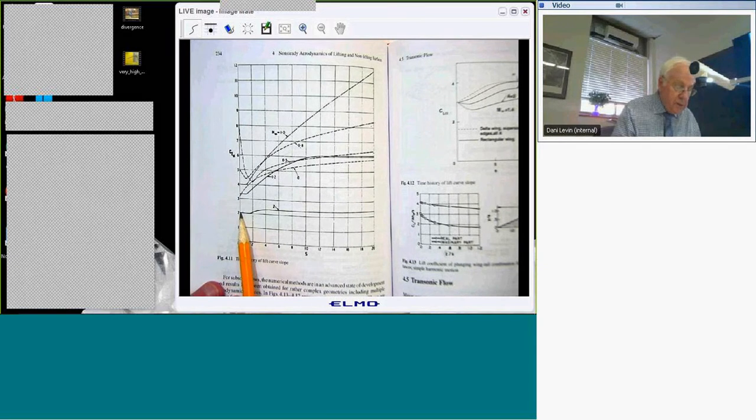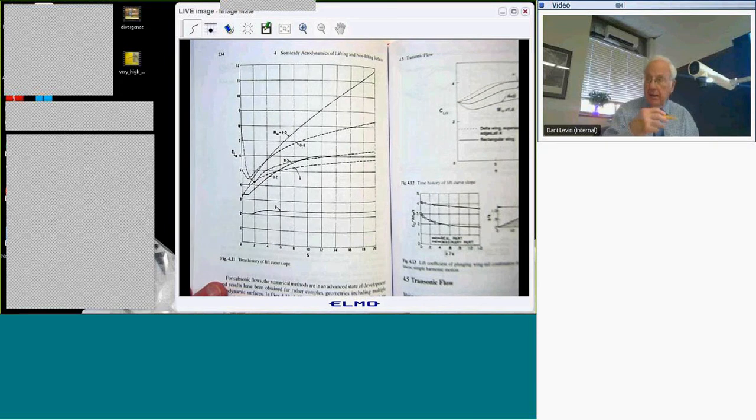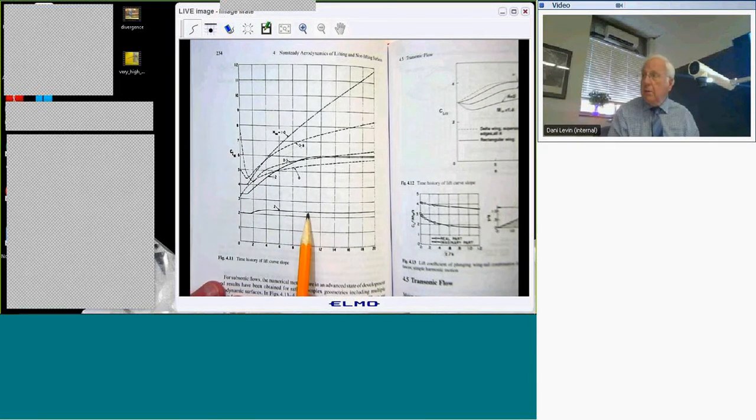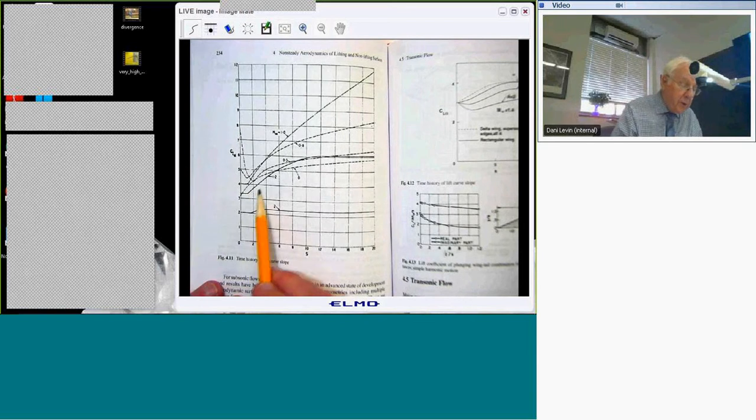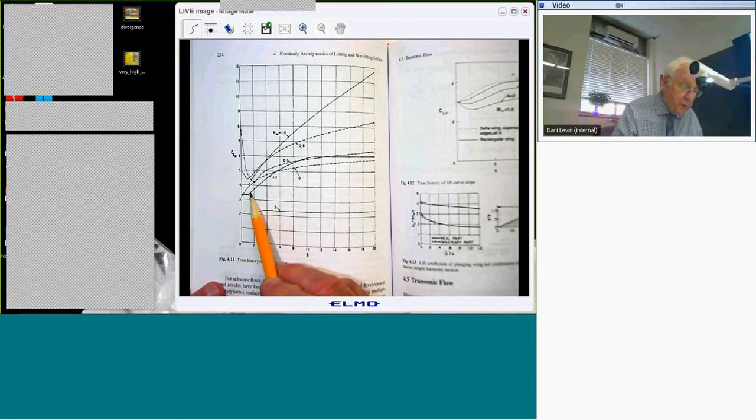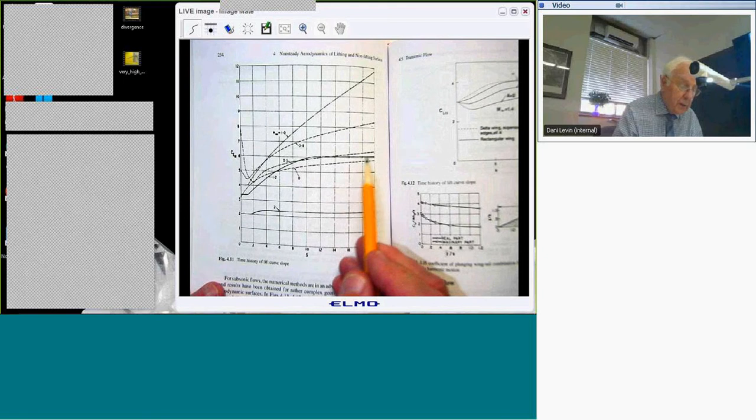There's an initial transient, which takes a while for things to change from piston theory, and that again deals with the propagation speeds. And then it quickly moves up to its final steady state value, and then doesn't change after that. Here's Mach number 1.2. Again, it's piston theory at short times, and then goes up here.